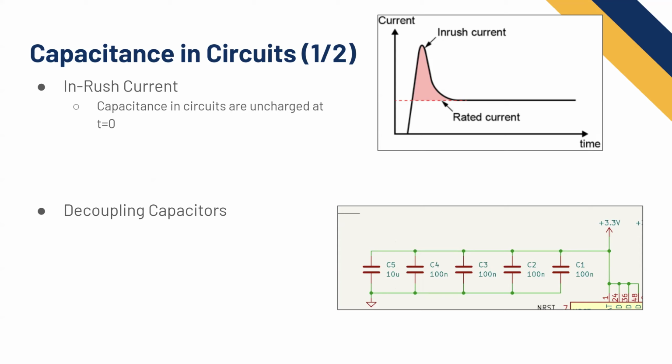And so instead of having your voltage drop on this power rail and your microcontroller browns out, you put these capacitors, and then the current will come from these capacitors to power your microcontroller until the rail has time to react. So that's what it means by decoupling. It's decoupling your input power from the load. And so this is done with microcontrollers. Every single IC that has power on your board should have a decoupling cap on its power pin. Yeah, it's a very common thing on ICs and circuit boards.